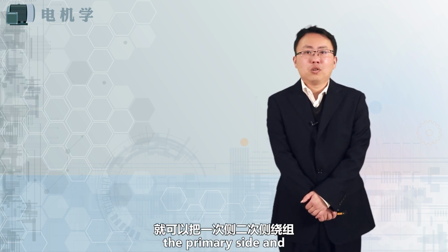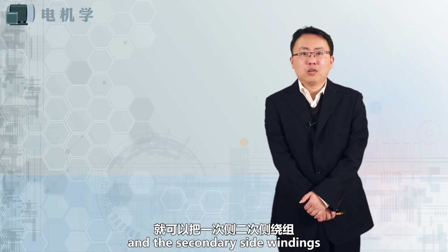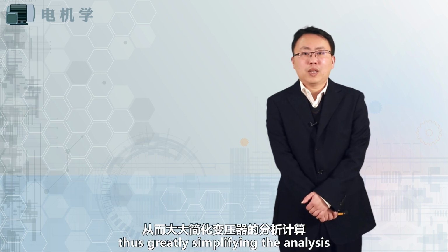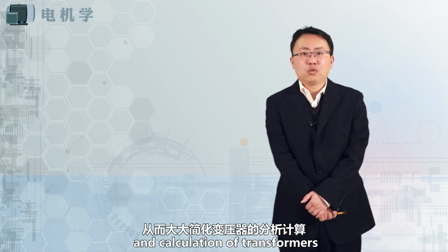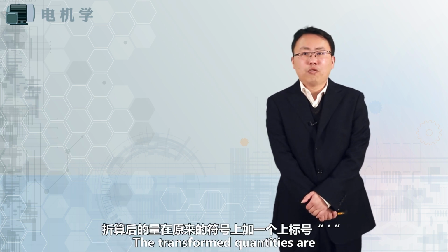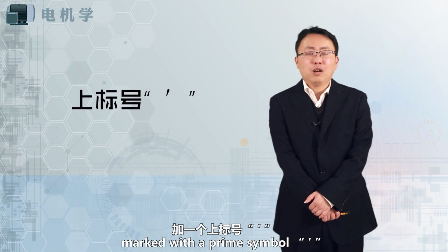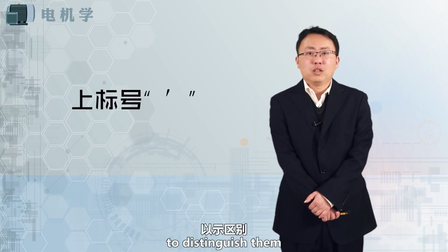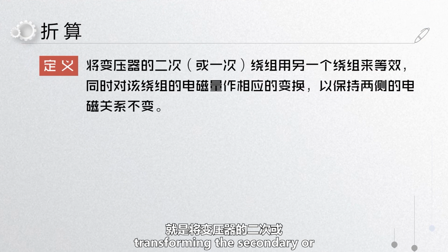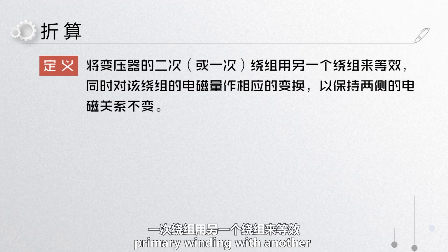In this way, the primary side and the secondary side windings can be connected into an equivalent circuit, thus greatly simplifying the analysis and calculation of the transformers. This method is called winding transformation. The transformed quantities are marked with a prime symbol to distinguish them. To summarize, transformer winding transformation means replacing the secondary or primary winding with another winding to make it equivalent.